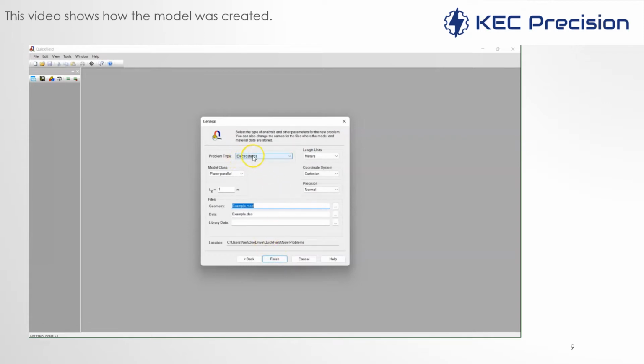and it comes up default in mine. In electrostatics, yours may default to something else, but we're doing AC magnetics. I'm working in millimeters in this model, but I'm using a North American 60 Hertz frequency. LZ is the depth in and out of the paper. It's common to leave that at 1000 millimeters, 1 meter.